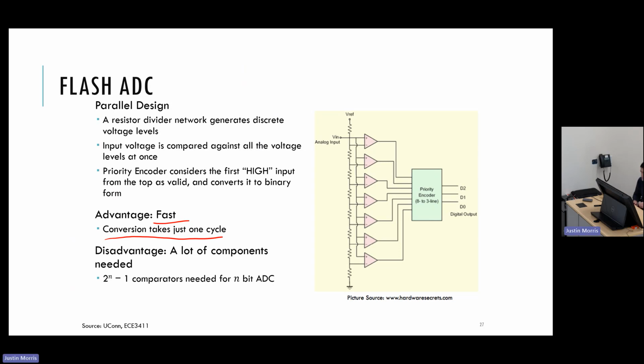The way that it does that is it creates this resistor network, and it is dividing up the reference voltage into these distinct ranges, right? With the resistors. And then it's doing this comparison with the input voltage. We have this voltage reference that we split up into the intervals, and then we have the input voltage.